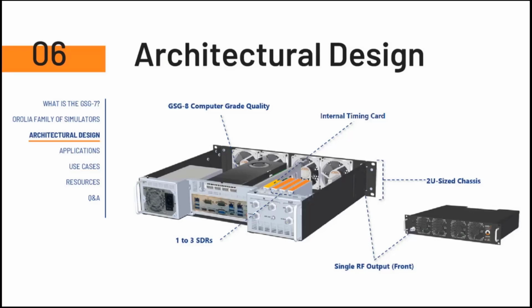Then in yellow, you have a timing card. It's the clock reference for all the radios. It's an OCXO with a very high accuracy, and it's possible with the embedded receiver to calibrate the timing card on the external antenna, to calibrate the simulator and its clock every year.